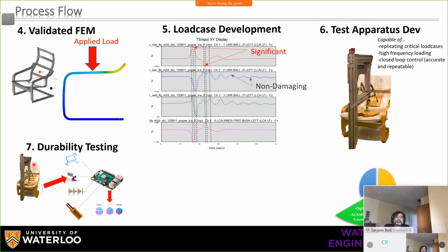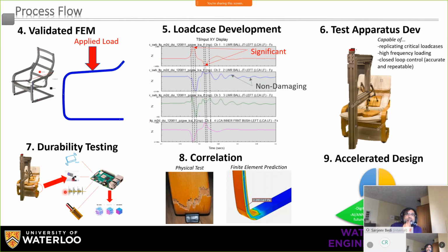But that particular margin of error that we're getting is directly correlated to how much factor of safety is there in the chair, and are we using more material than we really need in certain locations, and can we improve the performance of the chair, or can we reduce the cost, or can we improve the manufacturability or something like that. So the failure location that we're observing here in the actual durability test, we want to correlate that to the Ansys model here. All of the inputs that go into the Ansys model, such as the boundary conditions, the mesh, the material properties, what elastoplastic model we're choosing to use, the fatigue properties, the damage model that we're using to assess the fatigue damage, we're going to refine into a holistic model that we're going to call this Ansys model to improve the fidelity.